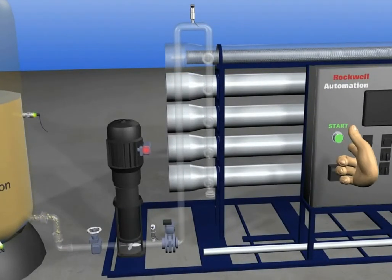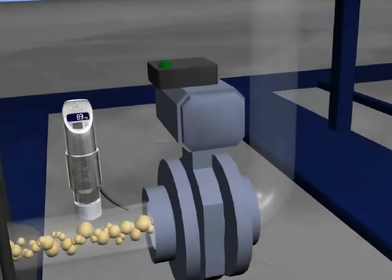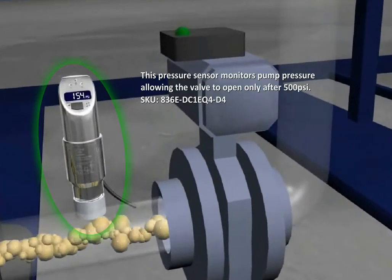Once the process is started, flow passes through the high pressure pump, where a higher feed pressure of 500 psi is created for the feed water. We are using an 836E display pressure sensor to check the feed water pressure. The 836E device is made of 316L stainless steel. It can be programmed using push buttons or PC software. Also, it is available in switch and 4 to 20 mA analog output versions.